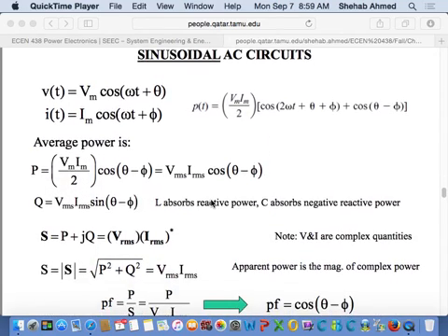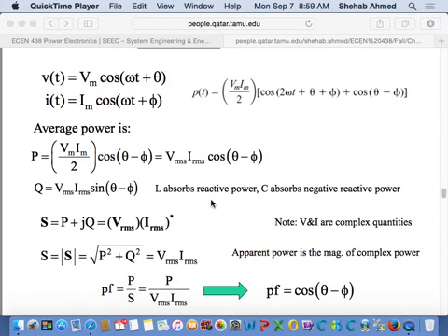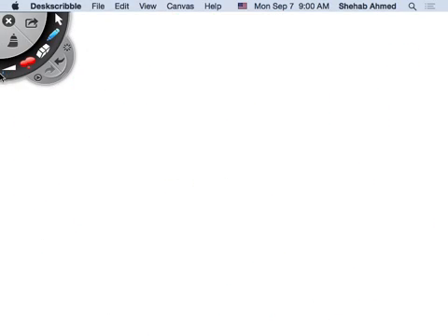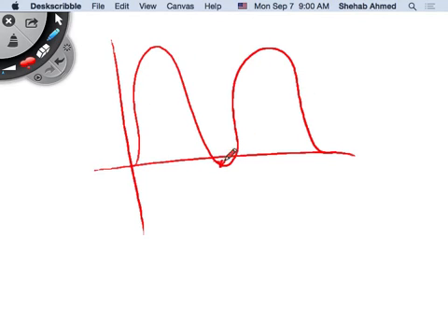Okay, I know it took a lot of time here, but this power triangle is very important, okay? So it's the next part I will go, we went through a lot of this. So something else that's interesting. We said that even in a system where I don't have a difference between voltage and current, the waveform for instantaneous power looked something like this, right? There's no negative, and it had an average value. This is instantaneous power in a resistive circuit, right? This was the V times I when they were in phase.